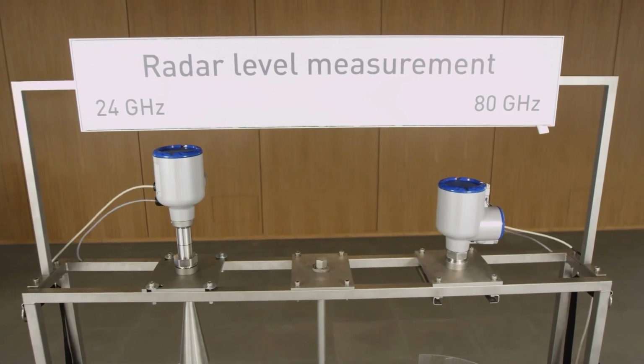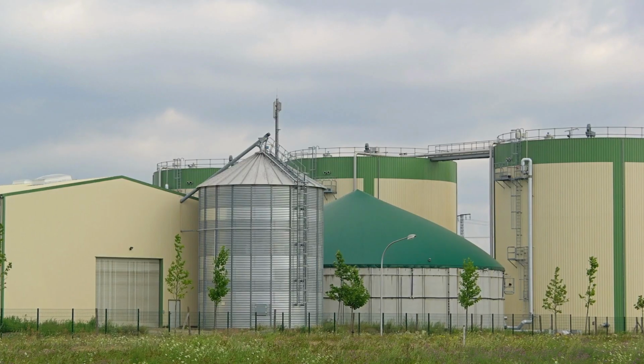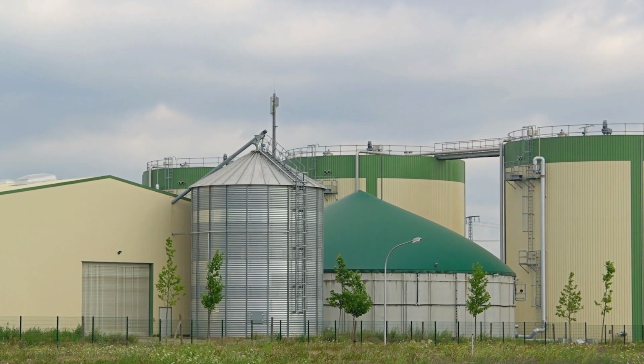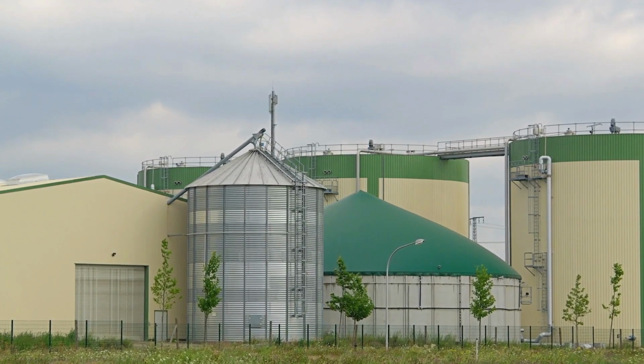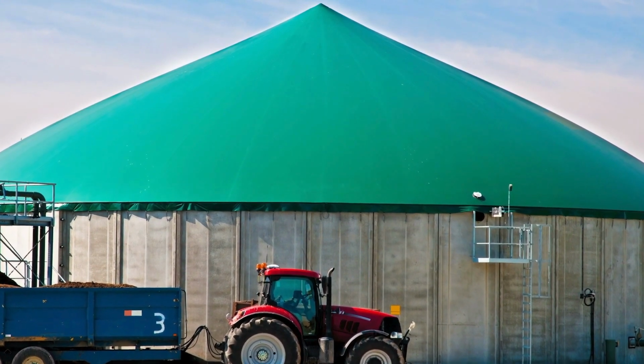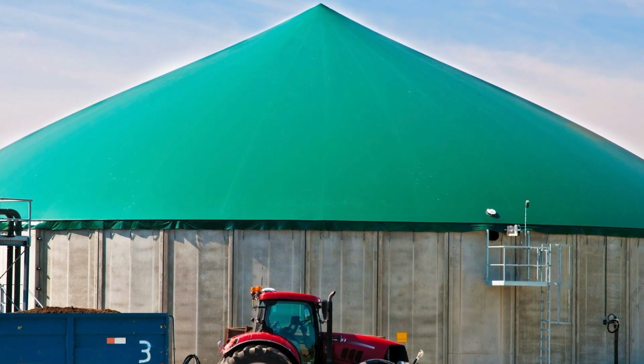Both radar systems are not only suitable for the measurement of low reflective products, but are also able to measure through tank walls or tank roofs made of plastic. Such applications are found, for example, in bioenergy plants, in the level measurement in the fermenter, where the measurement typically takes place through a plastic foil.